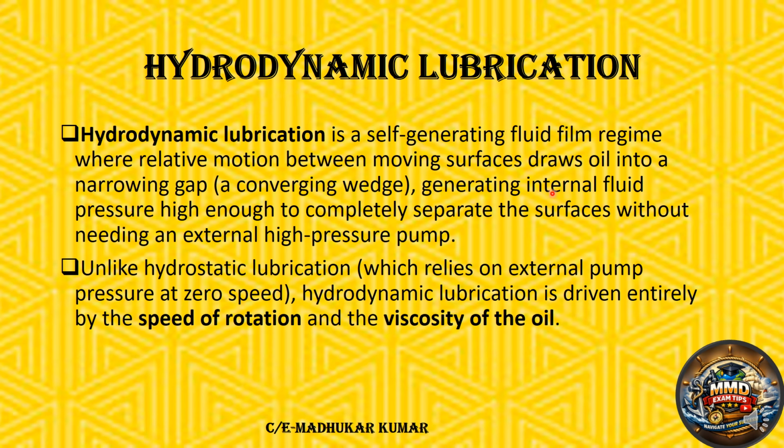And it generates internal fluid pressure high enough to completely separate the surfaces without needing any external high pressure pump. So once the relative motion has started, this is sufficient to generate the self-lubricating film and the separation will happen. Hydrostatic lubrication wholly depends on external pump pressure at zero speed, and hydrodynamic lubrication depends on the speed of rotation and of course the viscosity of the oil. So oil quality also matters.